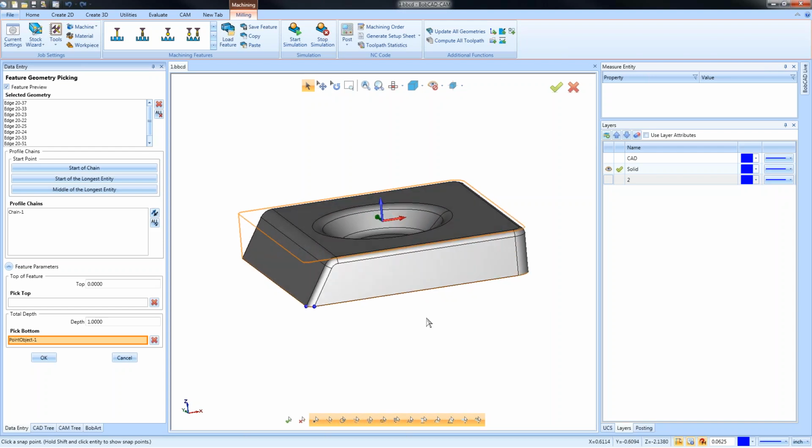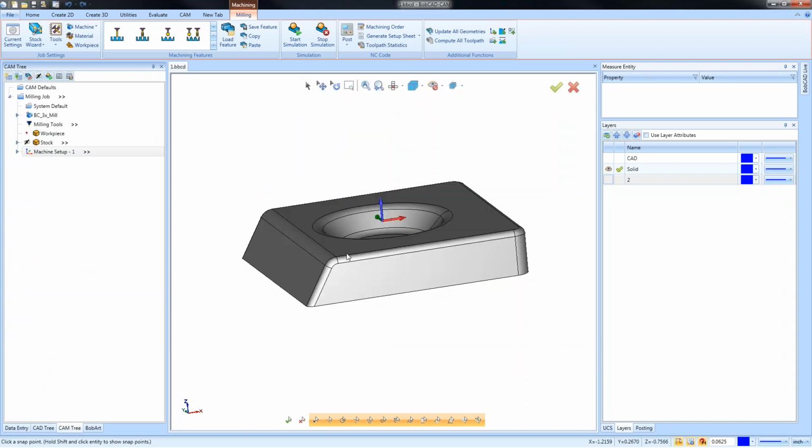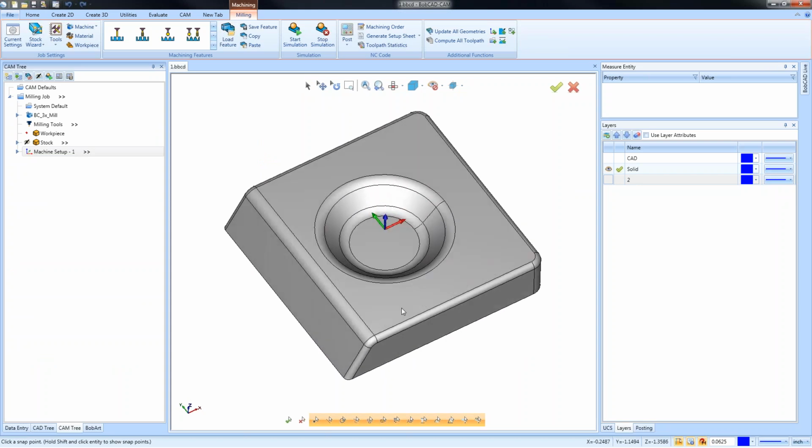You could argue you might be able to use taper tooling. Sure, that's true. But for the most part, with 2D machining, you're dealing with straight walls and a single depth for the geometry that you selected, and we're talking about drilling, pocketing, and profiling. Anytime you start to get into a taper or a slope, curved shapes, things like that, that's when we're going to get into 3D.